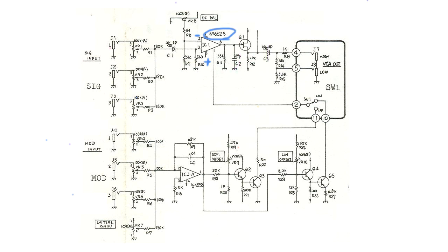So let's see what the gain is if we look at the output based on whatever the current flowing into the control pin is. And I'm going to call this IABC because that's how it's usually labeled on the datasheet, the amplifier bias current. I'll also sometimes call this I subscript CON for control. For this next bit of analysis, let me suppose that this capacitor isn't in the circuit. I'm just going to focus on this 33K resistor here, and then we'll talk about the capacitor later.